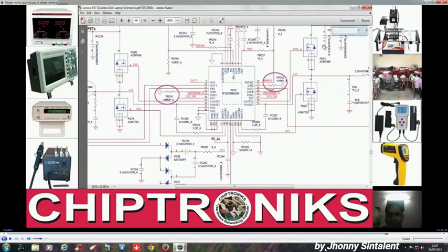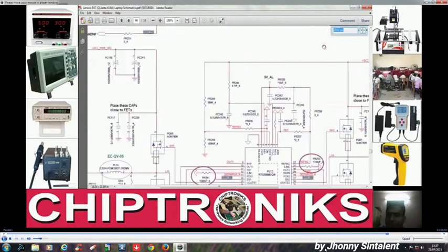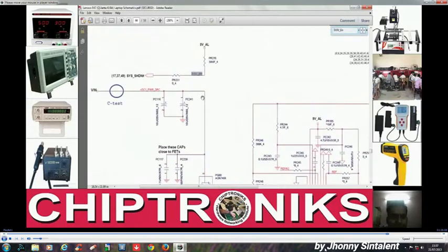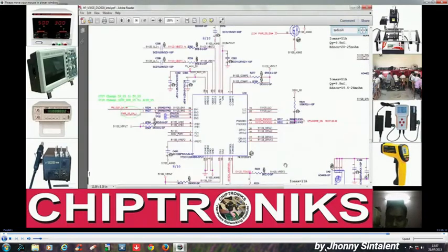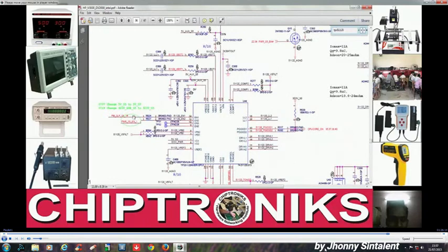We can search over here. 3V, 5V_EN. So where would they get connected? They are getting connected to the 5V_AL. And if we see DV2000, this EN1 and EN2 are fed from the IO controller and PC and ICH,